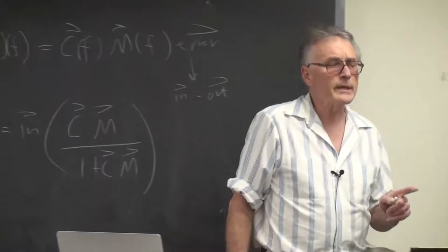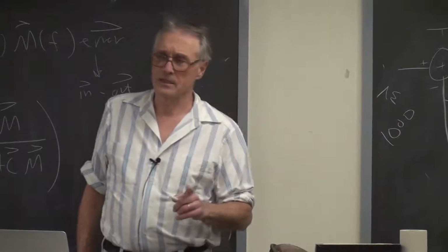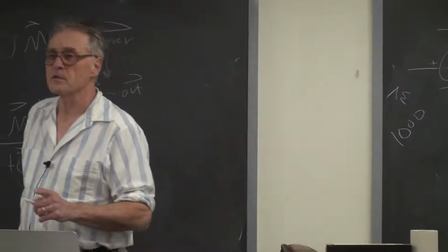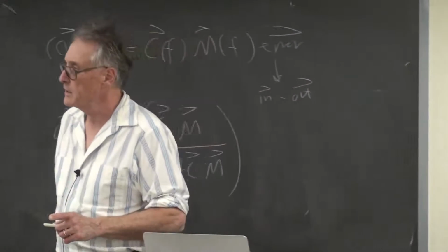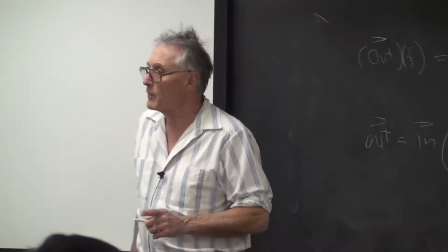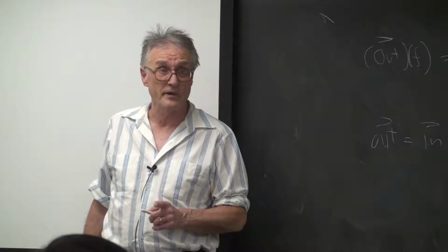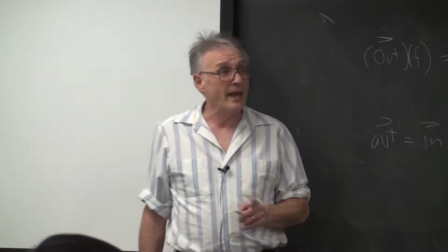if you choose a really large gain, then at high frequencies, where the phase shift is 180 degrees, you'll be subtracting a really large negative, well, you hope it's a negative number, but in fact now it's become a positive number because of the 180 degree phase shift. And you'll get gigantic overshoots.